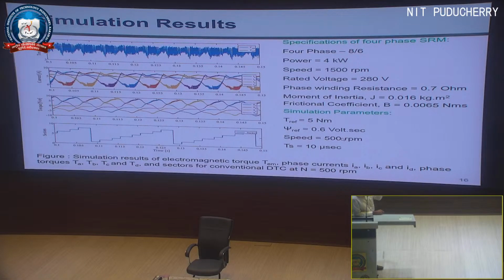So you don't need anything, because in the motor, the moment I give some supply to the stator, flux will be generated, and when there is a change in the flux and there is a stationary core, again an EMF is induced. So all those things will come into the picture. But what we are saying is that the stator flux vector is rotating in that fictitious 360 degrees, and based on that we are just trying to switch on and switch off the individual phases, right?